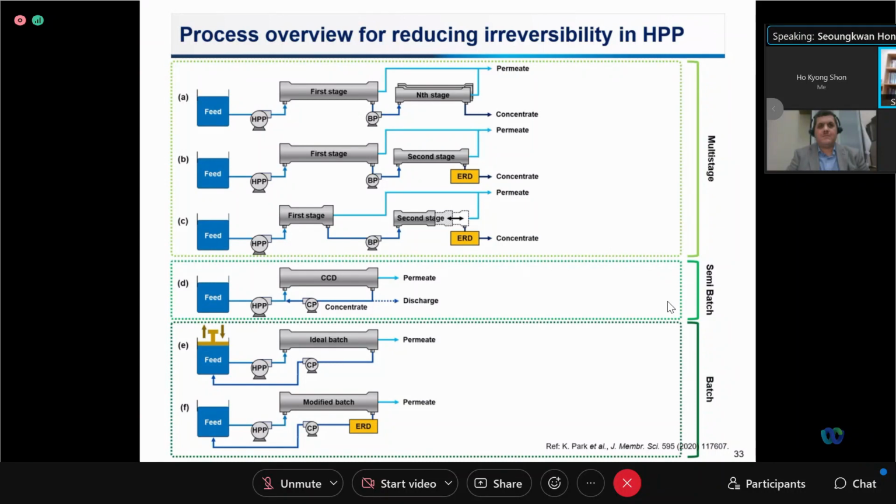The energy supplied to our system is used to separate water from the seawater feed, and an additional, different type of work is also associated with the process that is not directly involved in separation. This work is equivalent to the energy lost by entropy generation, which is known as irreversible work.